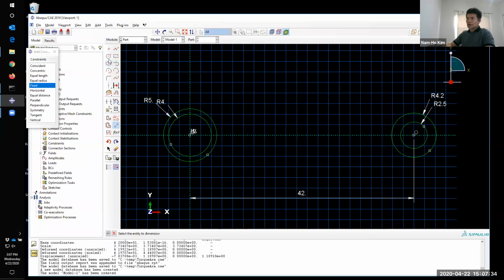I will make another circle. Later, these are not full circles, these will be arcs, but I start with a circle, okay? So let's make a circle here. And for this one, you need to provide horizontal and vertical locations. So I provide the dimension from this point to that point. So this is your dimension. Let's say this is 34.5. That's what is given in the project statement.